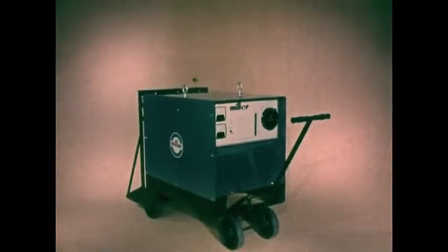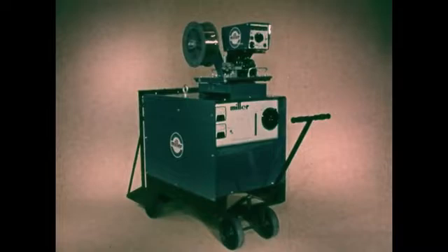One is the constant potential type welding power source, which maintains a relatively constant arc voltage throughout the entire current range of the power source. A continuously fed wire electrode is provided from a spool of wire positioned on a wire feeder and control unit. The control unit permits control of wire feed speed.